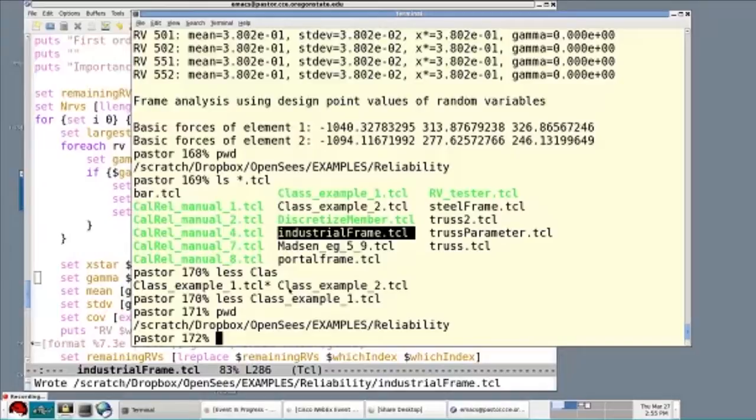If you're just looking at shear force being above or below a certain threshold, and you don't care at what time that occurs within an analysis, then Monte Carlo can certainly work. But you're going to be running a lot of simulations, 10,000 or 100,000 time history analyses. It's embarrassingly parallel, though, and could be forked out pretty easily to multiple machines.